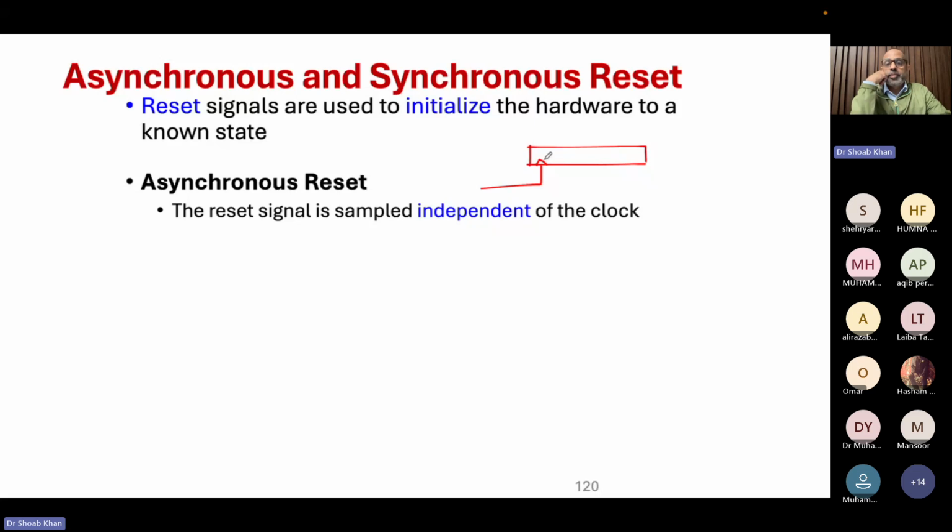So you need to make sure in your design that wherever there is a register, you have a resettable register, so that if somebody wants to do a soft reset, it just initializes. But if you are not initializing every register in your design, then you have to give a hard reset, and that sometimes is not good. So all the reset lines are connected with a button which says reset, or we can do a soft reset by asserting a signal onto it.